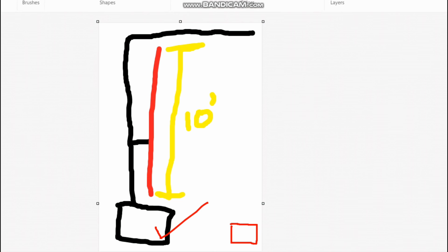So the AHU is here, from the AHU the duct is coming here, and after the VAV the duct is passing to the big room, and this red color you see here is a linear slot diffuser. The total length of the linear slot diffuser is 10 feet. So this is the condition. Also this duct continues to serve different parts of the room, and we have different slot diffusers. So here the issue is, I have taken only one duct connection to serve a 10 feet length linear slot diffuser.